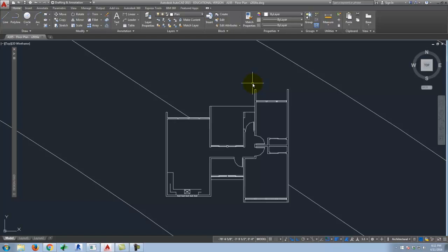If you were a structural engineer and you were doing structural drawings, you would do S-whatever, and that would differentiate you from the architect who's doing the architectural drawings. And so we follow that standard convention as a way of kind of organizing our files and letting us share files with each other and knowing who's doing what on what layer. And so for the scope of this class, it really doesn't matter whether you call it a wall or you call it wall, etc. But we're going to set up and move our objects to be on specific layers, and then we'll start to modify the properties of those layers.